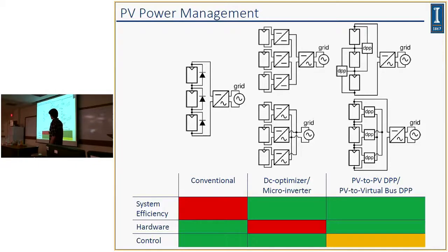So your hardware requirement is substantially increased. Also, because you're processing the power from that panel, you're potentially losing a lot of energy. Say each converter is 95% efficient, and the power generation from all three modules is like a kilowatt. You would lose 50 watts if each power converter is 95% efficient.